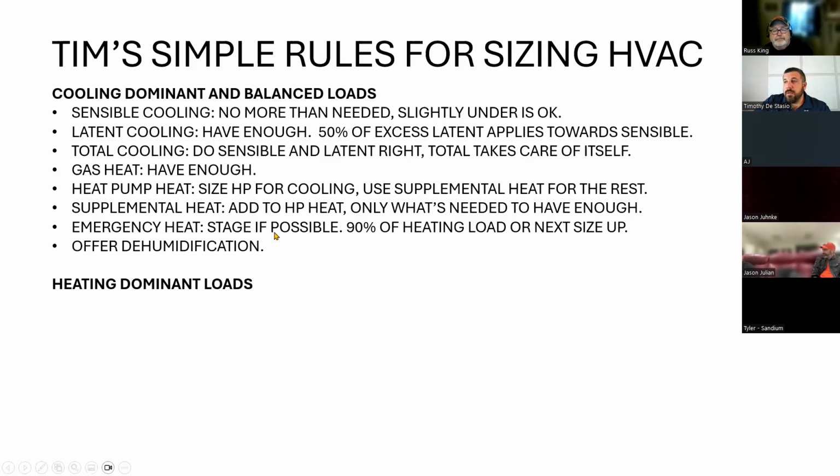The other thing is, I want to reiterate, when we're sizing a unit, we're sizing it for the only time it's hotter than that, which is like 1% of the summer. There are a lot of hours during the summer where even the best, most aggressively sized air conditioner is still going to be oversized. But your dehumidification load is still there. We're going to go over dehumidification load in a few minutes. But that's why I offer a dehumidification option on every equipment replacement that I do.